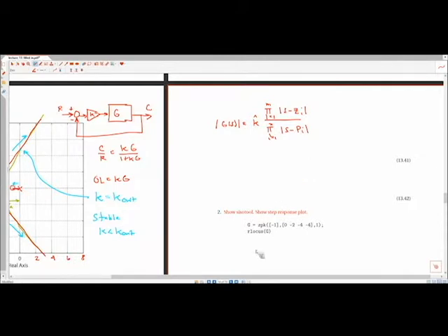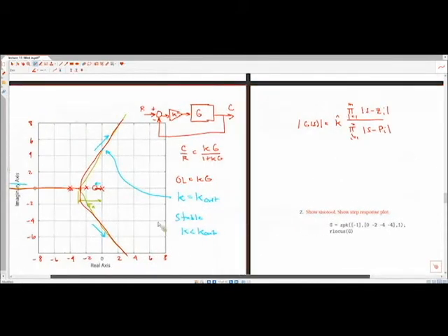Okay, so we know that, and this is coming from an approximation based off of our drawing, but we know that a pole pops into the right half plane at a value of S approximately equal to, just to use nice round numbers, somewhere around 5.